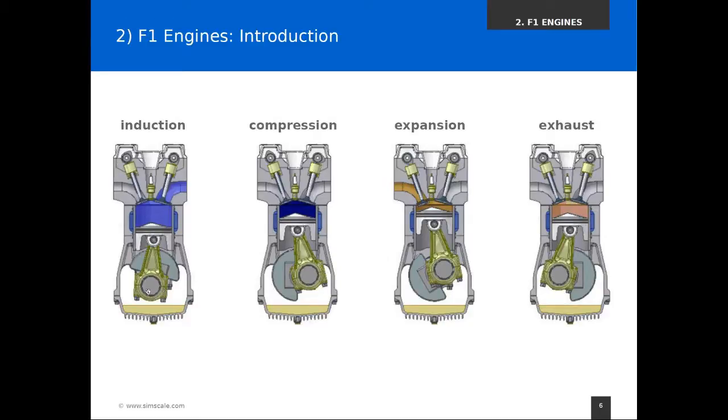So when the crankshaft does one full revolution, then the camshaft will do half a revolution. And the reason for that is, since we have a 4-stroke engine, the crankshaft will do 2 rotations, but the valves only do 1 cycle. So that's why the camshaft RPM are actually half the crankshaft's RPM.